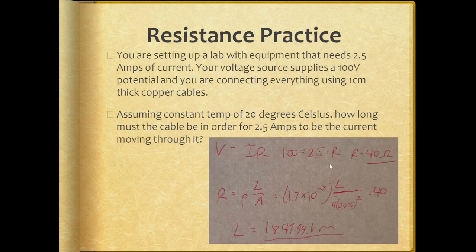So in this particular lab setting, if we have 100 volts, we need 2.5 amps. We can figure out that the wire would need to be a 40 ohm resistor in order to make that work correctly. We can plug 40 ohms in as...